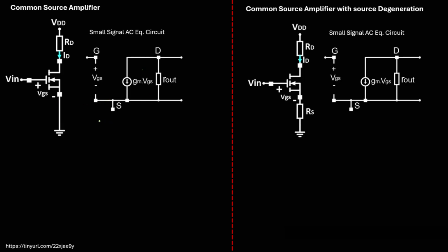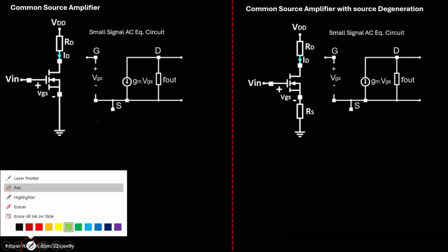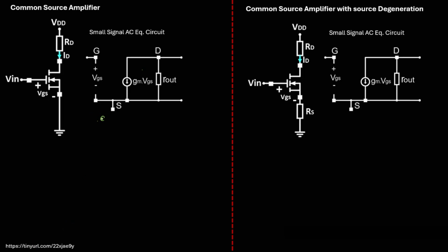When we do the theoretical calculation, let me take the parameter gain. As we know, the gain is nothing but V output by V input. V output is taken across the drain terminal of the amplifier, and V input is applied at the gate terminal. The source terminal is common because the configuration is a common source configuration. So this is drain, this is source, this is gate.